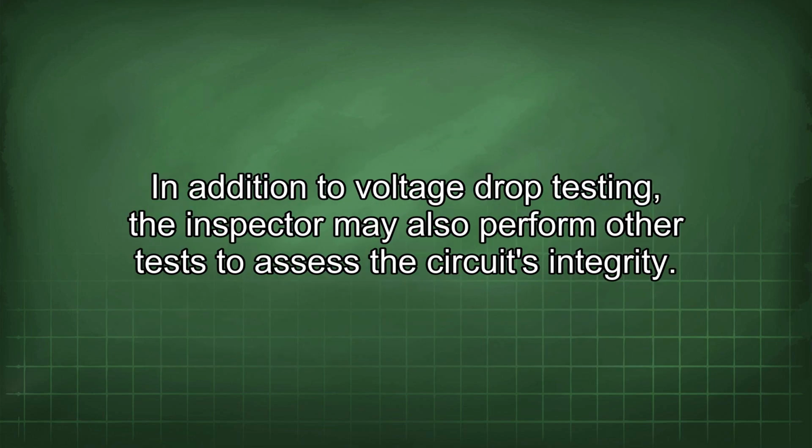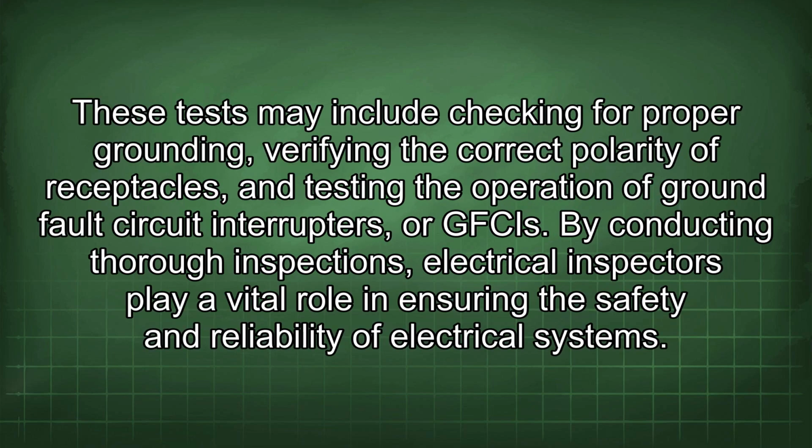In addition to voltage drop testing, the inspector may also perform other tests to assess the circuit's integrity. These tests may include checking for proper grounding, verifying the correct polarity of receptacles, and testing the operation of ground fault circuit interrupters, or GFCIs. By conducting thorough inspections, electrical inspectors play a vital role in ensuring the safety and reliability of electrical systems.